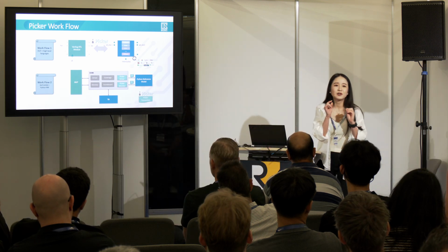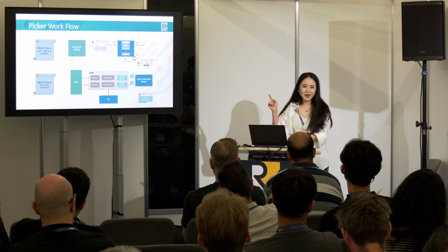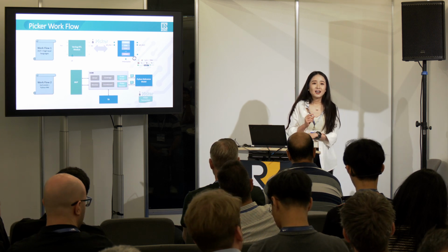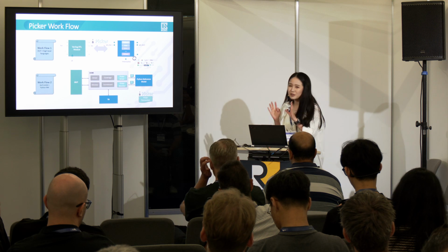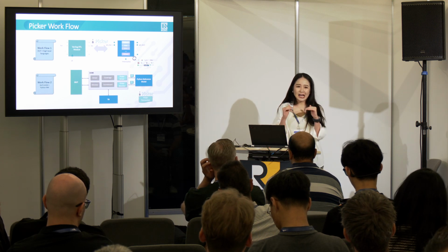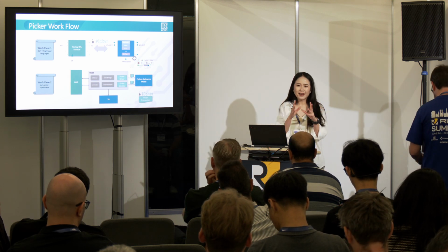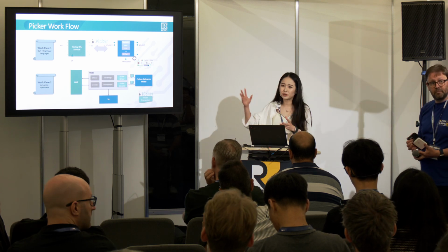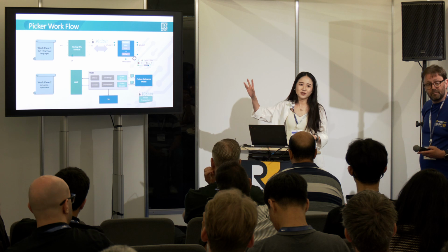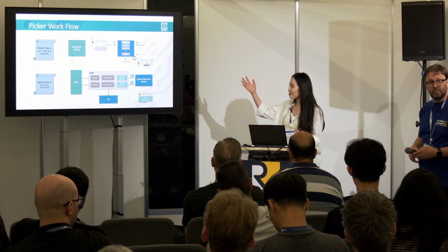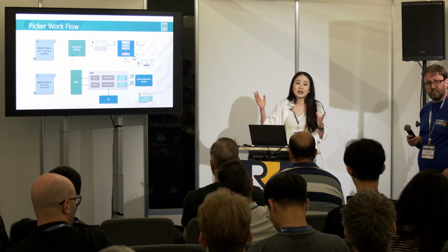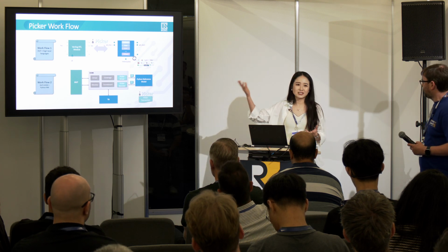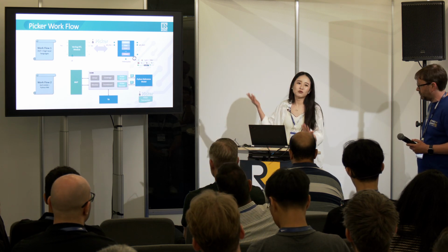To repeat your question, you're asking if in the first flow, is there something similar to the UVM methodology? In the first flow, there is no UVM. You can define your own verification methodology for sure. What we are doing here is to expose a software API so that you can write your Python, Java, C++, whatever software language you like to drive your DUT as well as your reference model.